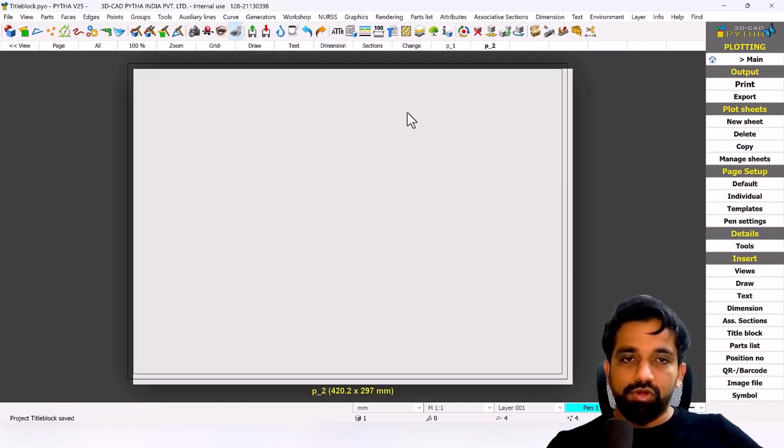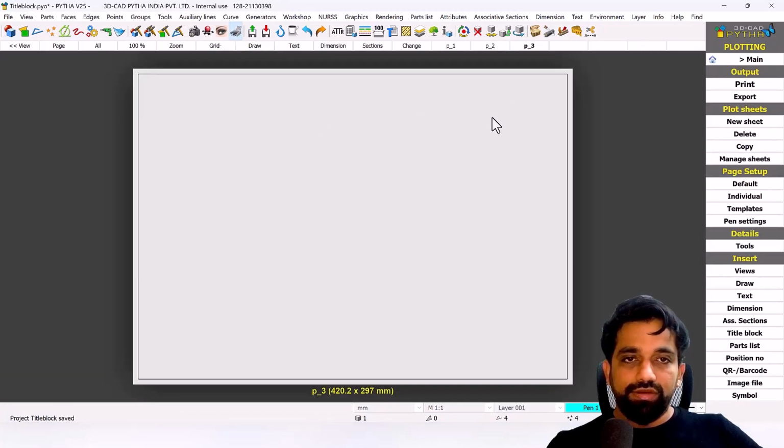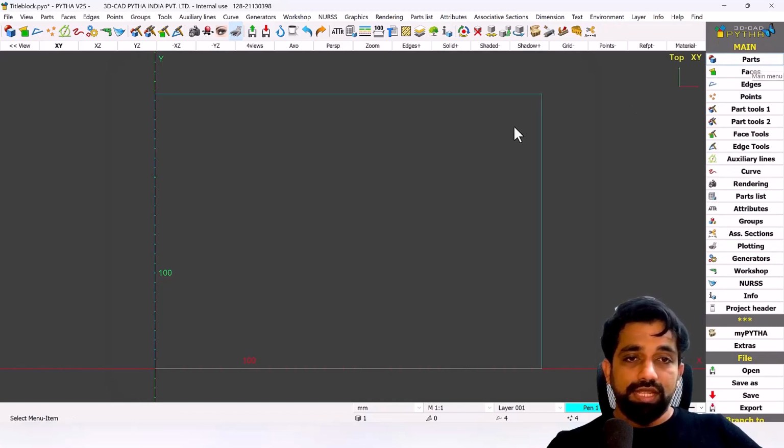I come back to the plotter again, and now let us check here. So whilst loading the third page, I can see it's perfect now. So always do this, just align your inner area to the origin and you have to delete the outer border.